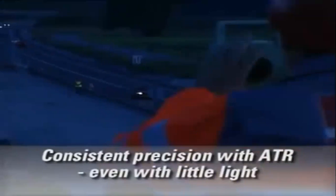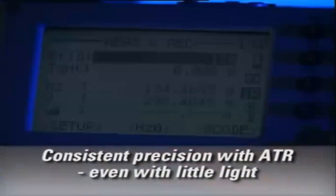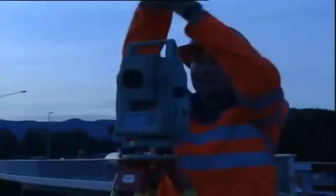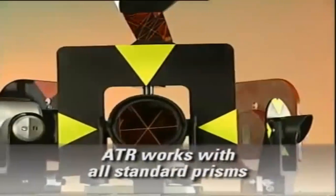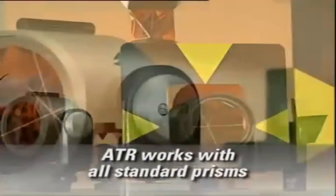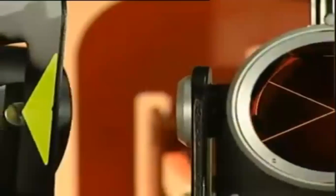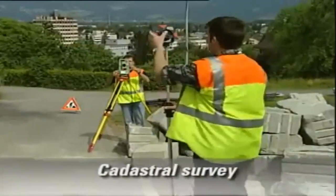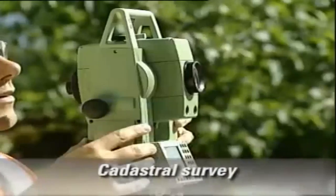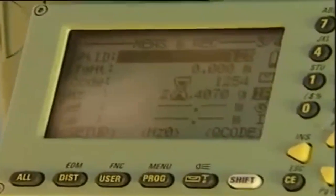Automatic target recognition provides consistent precision in all situations, even at night when prisms are no longer discernible by the unaided eye. One more advantage: automatic target recognition does not require special prisms or power supply. Just continue using the prisms you have, irrespective of the manufacturer, whether for cadastral plans or for topographic surveys. Wherever many points have to be measured, the TPS 700 instruments offer a lot of advantages.